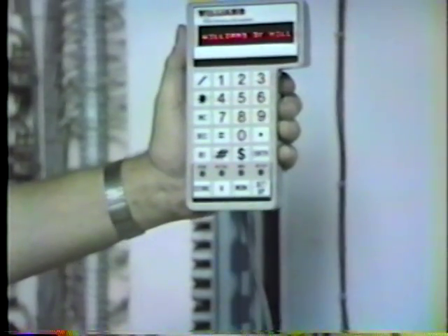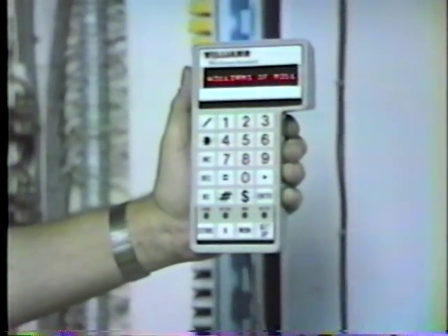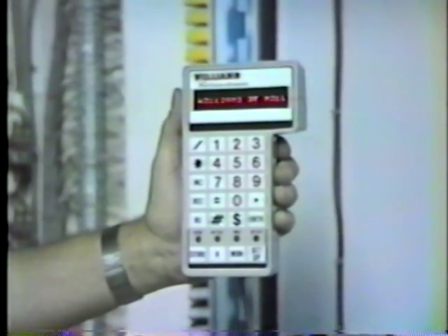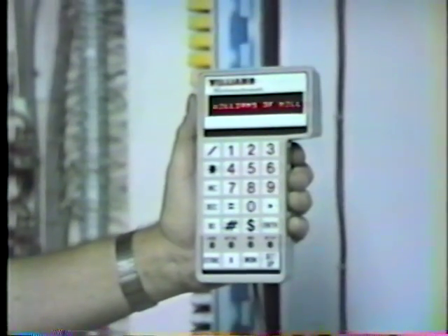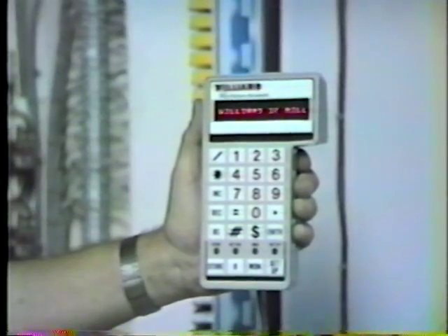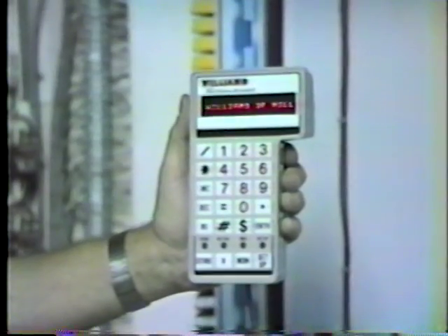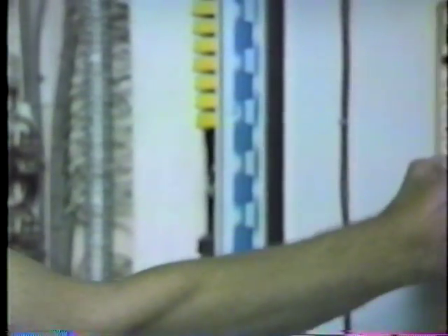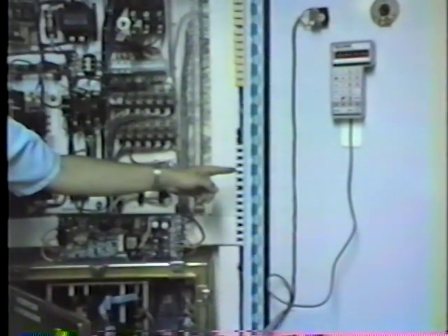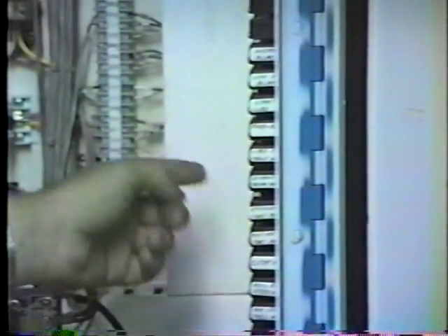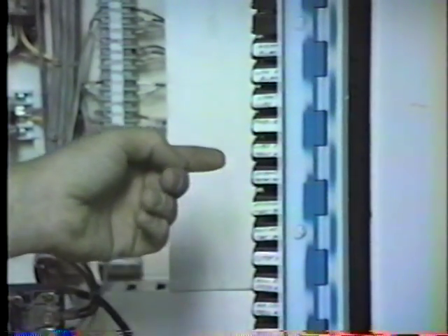Now how does one go about finding out exactly what tripped it off of the Williams panel? We recognize the fact that Forney will be showing us what tripped, but how could you also see it at the Williams panel? Well, here at the Williams panel, you go over to the output devices, the black solid-state relays. The ones that we looked at before, right? And they're labeled, and they say things such as spinner start failure, exhauster motor failure.